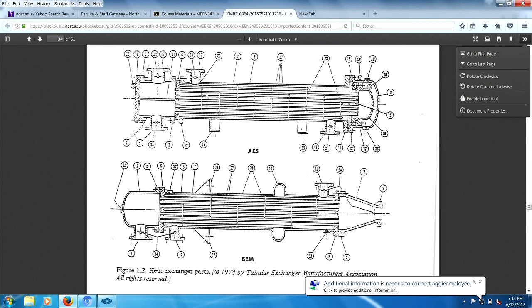The first thing you want to do is see about their welding capabilities, their certification, and how they store their tubes. Now, if the tubes are up on a rack, that's pretty cool. However, if the tubes are laying down in a pool of water on a concrete floor and there's about 30,000 of them, you probably want to turn around and walk out. You don't want to deal with somebody who can't keep their materials protected.